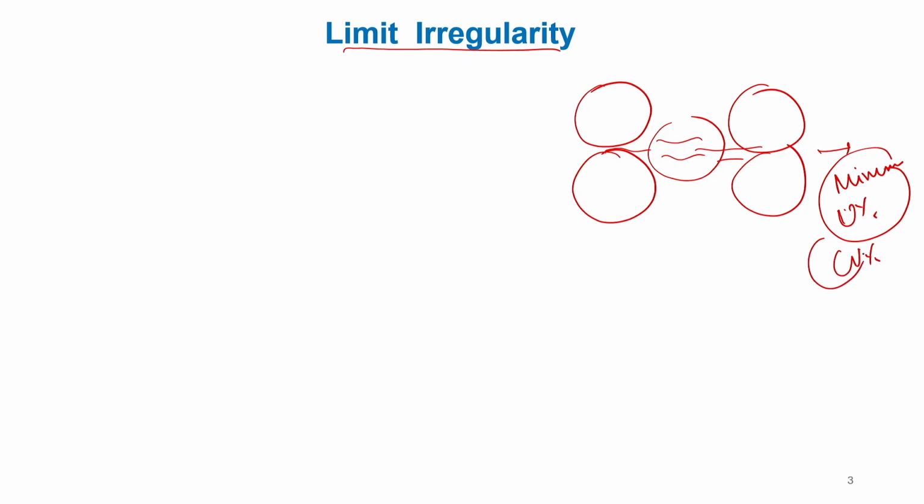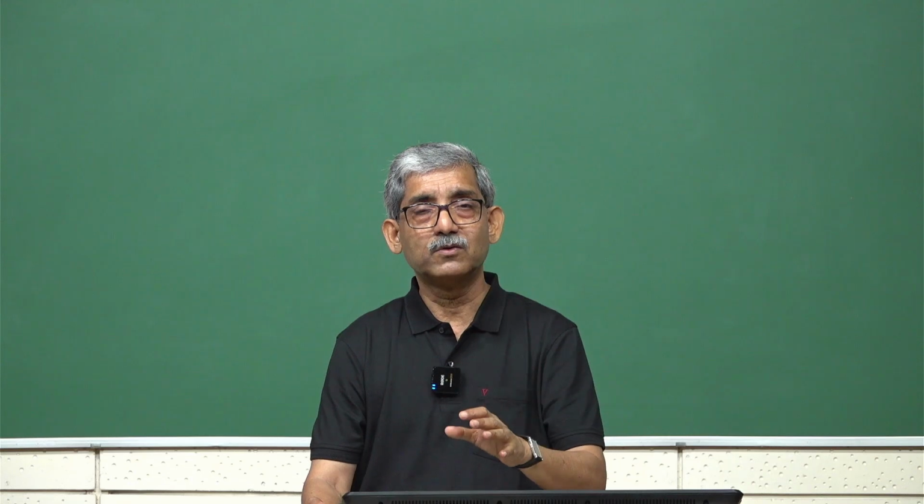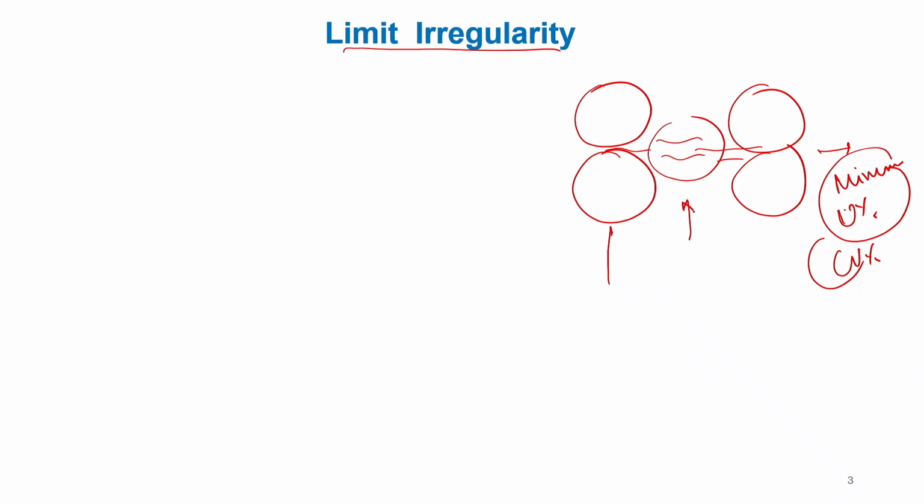Even if we use an extremely efficient, very good quality, new machine, and we maintain the best fiber quality, the best possible environmental conditions, the same machine settings and conditions, and no vibration, still we will get certain variability. That is because the present system cannot control the fiber movement positively.